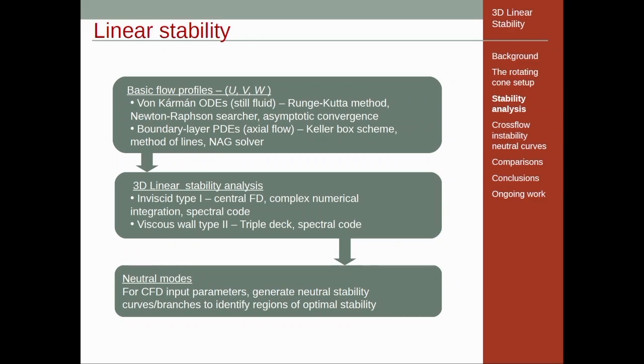That's a viscous wall layer instability mode, with a thickness of 1 over Reynolds to the 2/3, I think. Attacking both of these asymptotically, we can get some results. And if instead we simply discretize the equations, the eigenrelation, we can find numerical solutions as well, and hopefully compare the two.